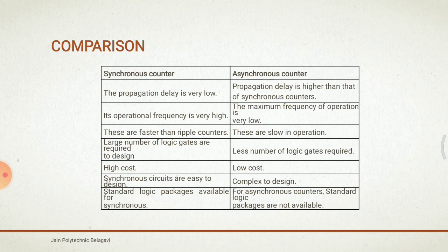A larger number of logic gates are required to design synchronous counters; fewer logic gates are required for asynchronous counters. Synchronous counters are high cost; asynchronous are low cost. Synchronous circuits are easy to design; asynchronous are complex to design. Standard logic packages are available for synchronous counters, and for asynchronous counters standard packages are not available.